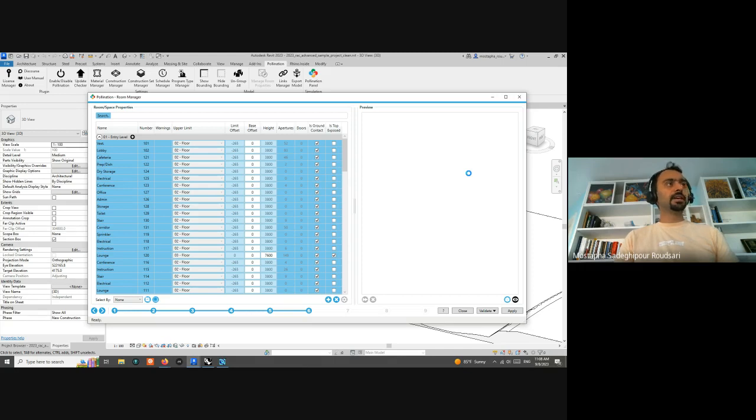One thing to know is that for this model, I'm just exporting everything together. But my suggestion, and you will see that in our video tutorials, is to do it story by story. So you can see the possible errors that can happen, and then you can fix them as they come. So let's give it a few seconds, and then the model should show up.